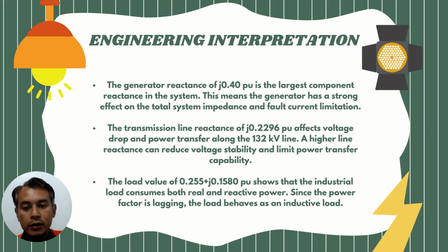The third point, the load value of 0.255 plus j0.1580 per unit shows that the industrial load consumes both real and reactive power. Since the power factor is lagging, the load behaves as an inductive load.